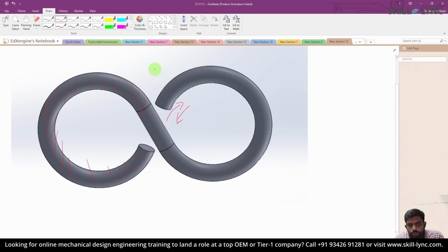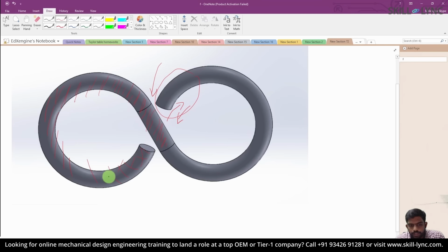So here in this model, in real life we fix this particular portion of the hook, and bend the other section to enable the connecting member to slide into this part. This portion of the member is bent and rebent to accommodate the connecting member. We are going to apply the same load here. I'm going to fix this region by a fixed geometry constraint, and after doing that I'm going to subject this particular portion of the member to a force of 50 newtons and apply a load and predict the life of this part when subjected to 1500 cycles. So let's go back to the presentation.